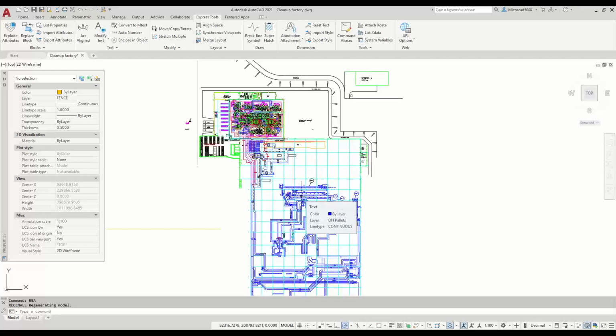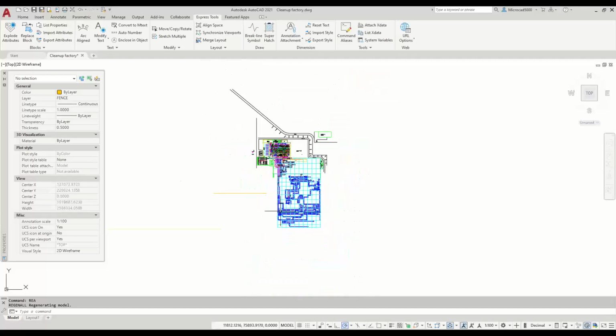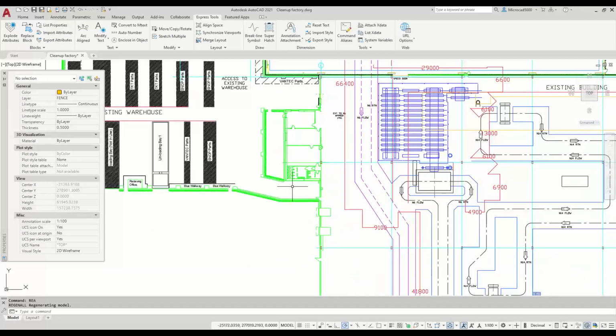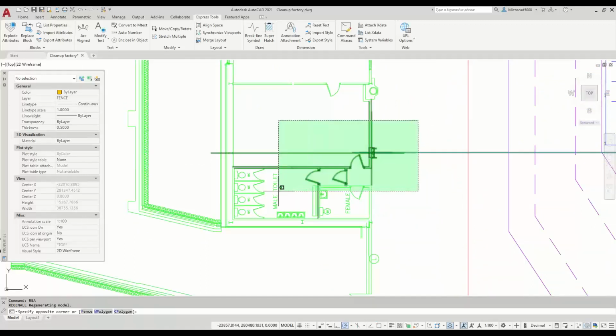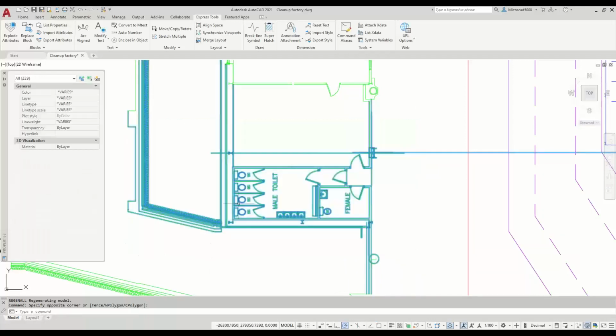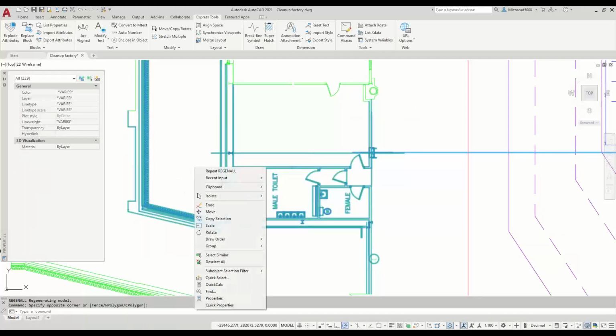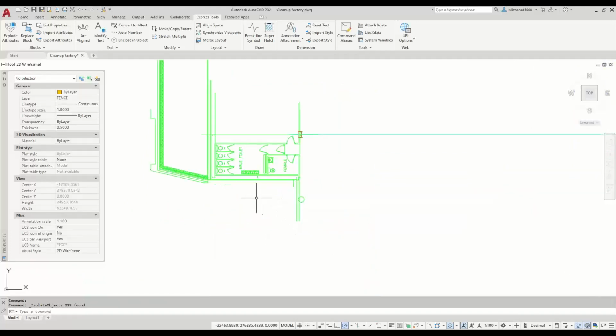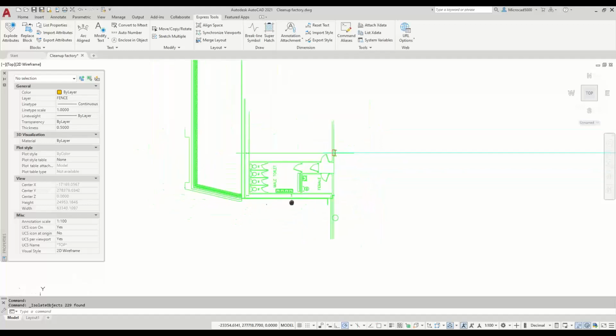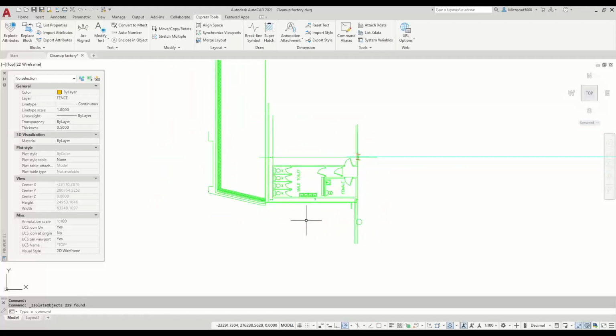Right. Other tools help speed up working on a big drawing. Supposing I'm only working in the toilet block down here, doing some layouts in this toilet block. If I select these objects in this working area, do a right click on the screen, there's a tool called isolate, and I can isolate these objects from everything else on the screen. It doesn't work like layers; this works on just the objects themselves. So now the drawing file is working a lot quicker, zooms in and out quicker, because it's just turned everything else off on the screen.